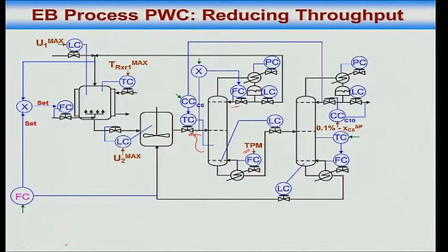Now in this case, what we have done is, we have gotten robust control of the level in the first column, which was not being controlled properly because there was a very unconventional loop there. What are we losing? What is it at the expense of? It is at the expense of large swings here in this loop, because now the control of this is being done by ethylene.